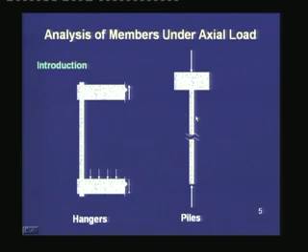On the right hand side, we see a pile which is subjected to axial compression, but piles can go to axial tension also when there will be uplift under high lateral force on the building, and the piles are also subjected to shear and bending moments. In these sketches, we have shown only the vertical forces. The ties are members which are horizontal and are subjected to tension.